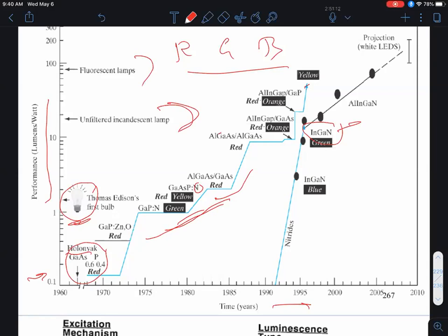Now, some of the technology that I haven't talked about is you have to be careful when you design these structures. So if that's my PN junction diode, say, suppose I have electrical contact over here, then I have electrical contact at the edges, I forward bias the thing, you have recombination of the electron hole pairs, and light comes out, okay? But when the light comes out, suppose that light hits the surface in this direction. Well, remember, this is a semiconductor. Outside I have air, but the refractive index equals 1, but here the refractive index is much larger, okay? It's of the order of the square root of the dielectric constant.